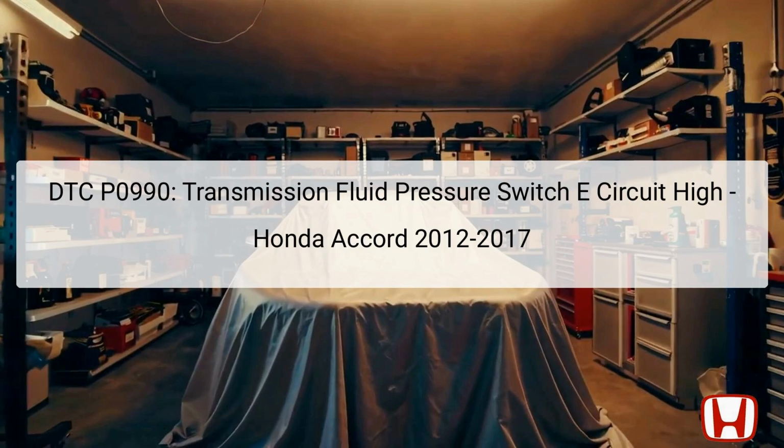The pressure switch is integral to monitoring and controlling the hydraulic system's operation, assisting the powertrain control module (PCM) in ensuring smooth gear shifts. Located in the hydraulic circuit related to the 6th clutch, its primary function is to activate when pressure is applied and deactivate otherwise. If the signal remains high while the vehicle is in 6th gear, the PCM interprets this as a fault, triggering the DTC, which in turn illuminates the check engine light and can lead to drivability concerns.